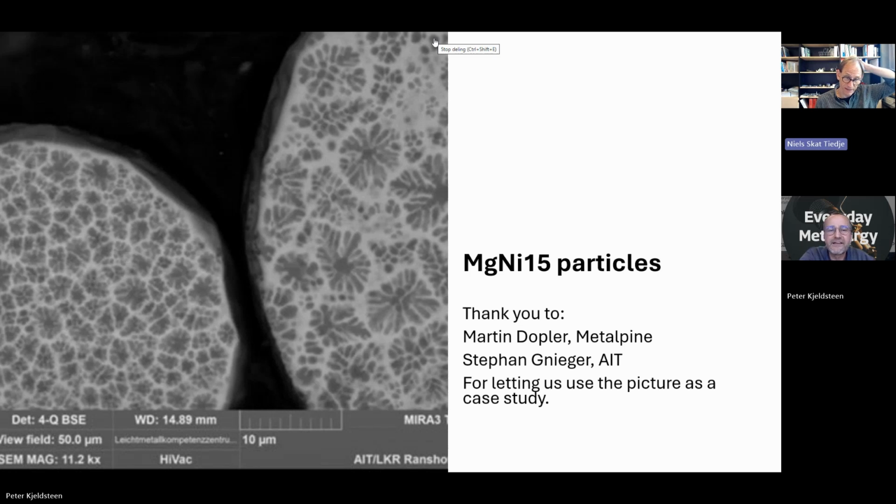It's a lovely picture, and it's a very high magnification, as you can see from the yardstick at the bottom, which is 10 microns. So these particles are maybe 50 microns across. And as you said, they are clearly very rapidly cooled. Therefore you see all these flowers, which metallurgically are called dendrites. Because they resemble trees: if you take a pine tree and cut a slice perpendicular to its growth, you see the stem in the center and the branches coming out, and this is what we see here. It's a tree-like structure. It has nothing to do with trees, but they look like trees.